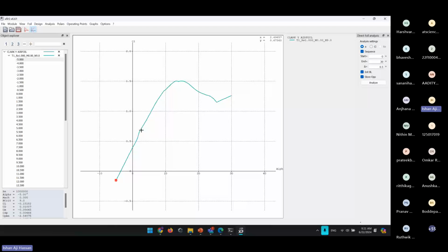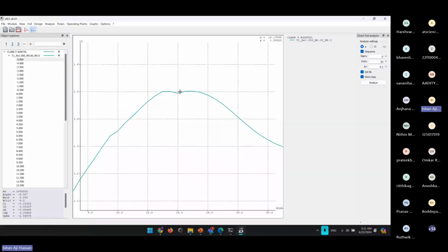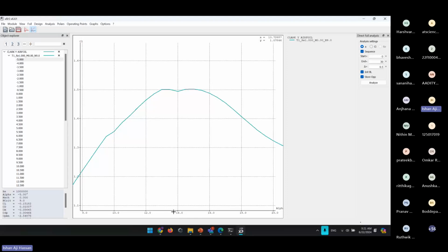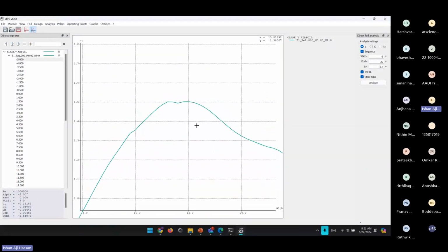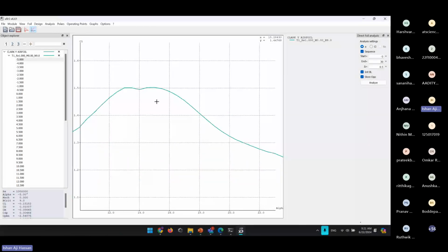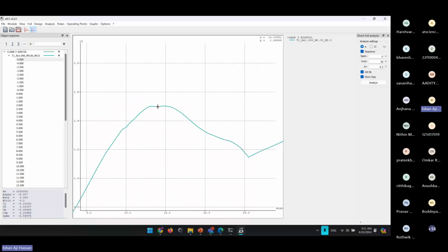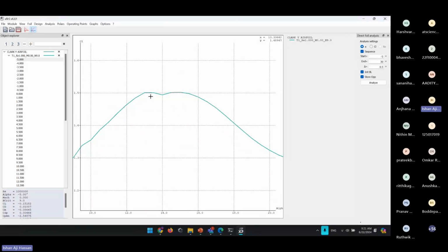What we can see is that as the angle of attack increases, lift coefficient increases linearly up until a critical angle. If you zoom in close enough, you can see it's around 14 degrees. If you increase the angle of attack of the airfoil any further beyond 14 degrees, you'll start to get stall and those issues. So ideally, we always want to operate below this range. Once you start stalling, you lose lift and you'll start to nosedive basically. So this is a situation always to avoid, what is to the right of the critical angle.